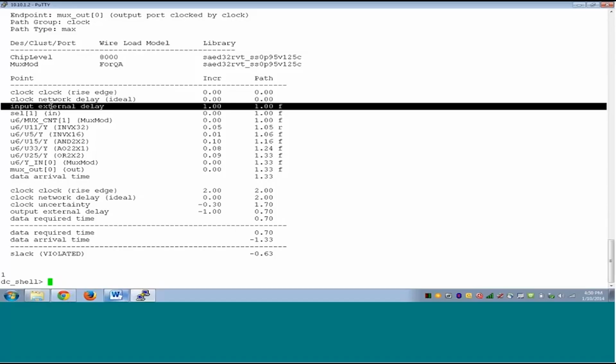So in this case, what we could do, I'll come to this a slide later, but for such cases we have to make sure that our input delays and output delays are not in such a way that such kind of combinational paths are constrained like this. It is a very bad constraint because it doesn't leave anything for the internal design, right? It will give all the timing away at either input side or the output side. So practical solution would be to reduce the input delay or turn off the output delay. There is one more solution, I will come to that later.